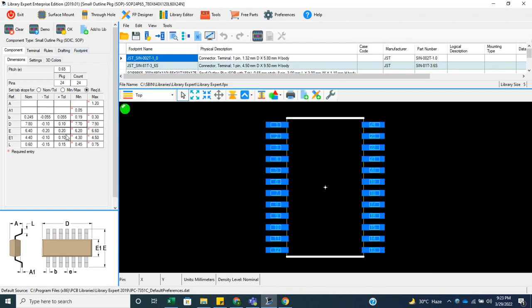In the demo section, when you click demo, whatever type you have selected, that means SMD, through hole, SOP or SOIC or QFN, whatever kind of package, it will be filled in automatically. So I have created one with the help of the demo. I have created one SOIC named SOP 24P65, and this is the standard IPC standard PCB footprint name.